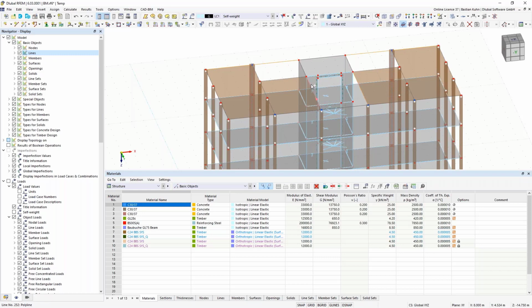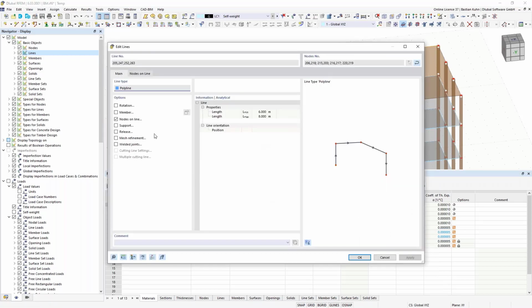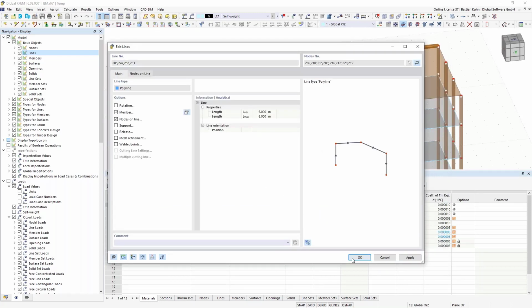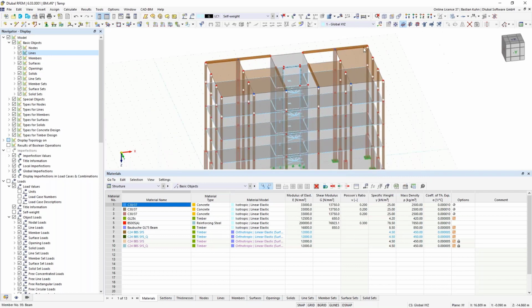Well, for sure, we will need some beam there. That's going to be a new member. And also a new section. We will choose the section 18 centimeters by 22 made from glulam. All right, member, and then we have it in here. There's something that has not been divided correctly. I will do so now. Yeah, looks good. Okay, there was something that looks strange to me.